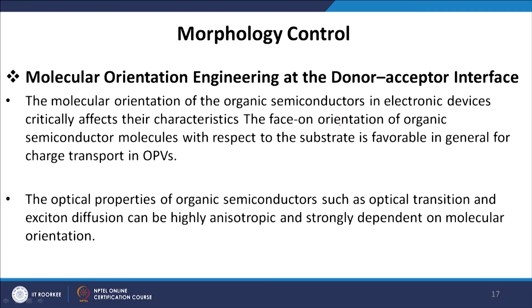Molecular orientation engineering at the donor acceptor interface. The molecular orientation of the organic semiconductor in electronic devices critically affects their characteristics. The face-on orientation of organic semiconductor molecules with respect to the substrate is favorable in general for charge transport in the OPVs. The optical properties of organic semiconductors such as optical transition and exciton diffusion can be highly anisotropic and strongly dependent on molecular orientation.